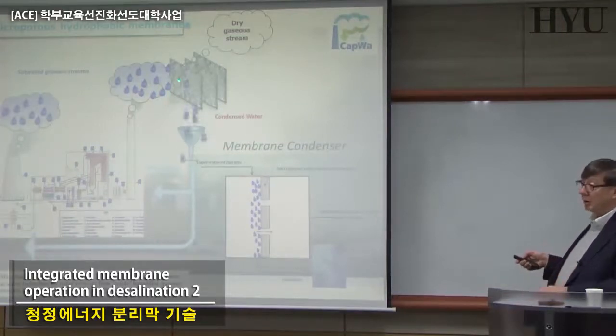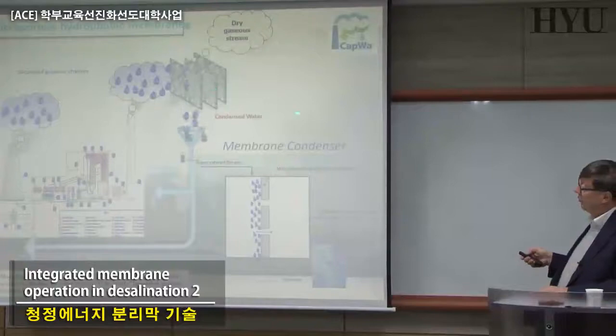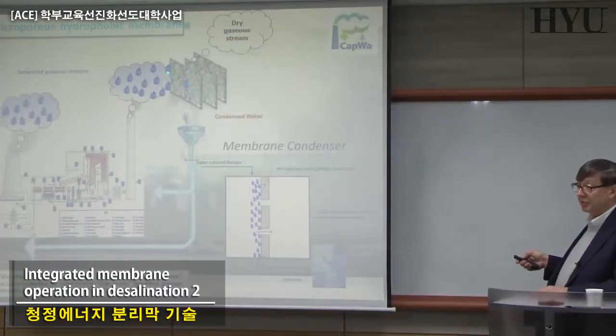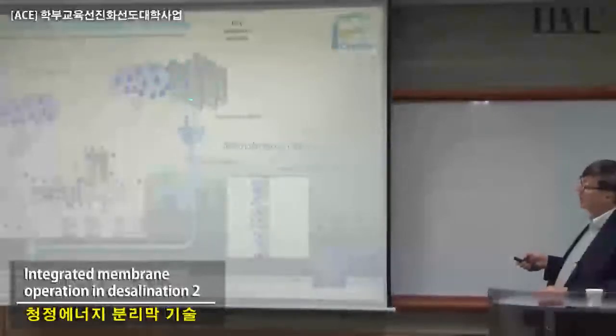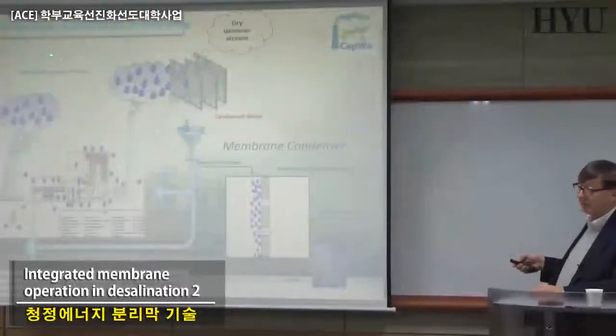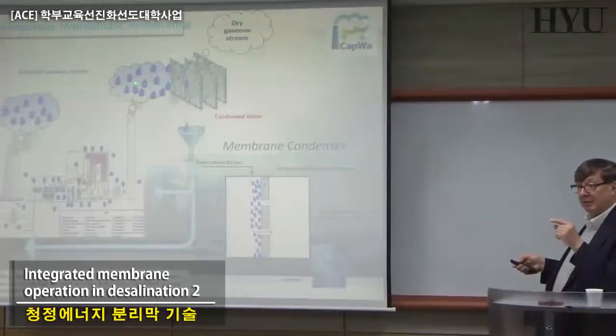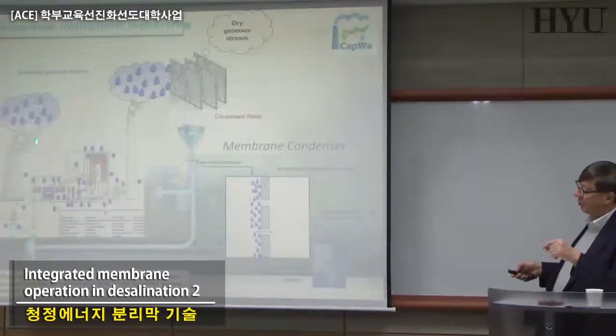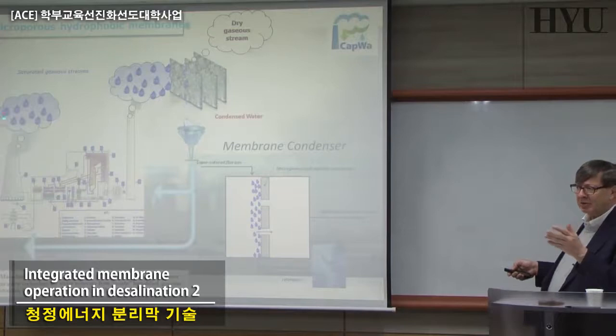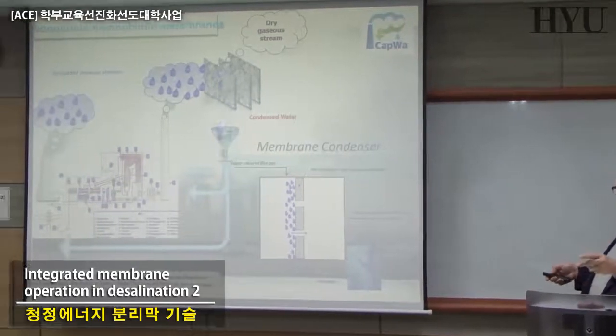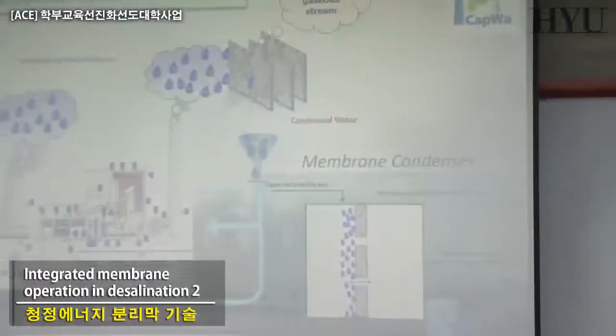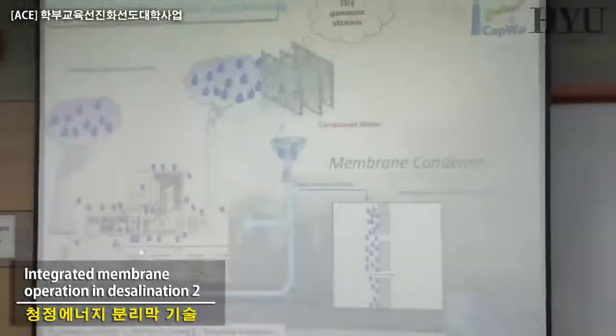And also here you're learning that when you compete with a normal condenser, there's something interesting. Because by playing on the typical membrane parameters, you can check the amount of contaminant. When you go out here, it's not just water and nitrogen, there's a lot of contaminant. Here you can have hydrofluoric acid, you can have ammonia, you can have SO2, you can have a lot of stuff coming from the process that you are considering.